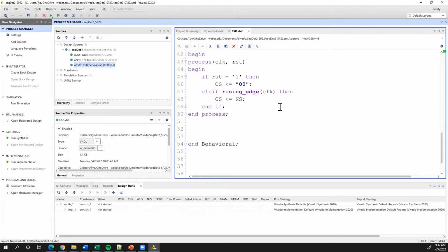One thing I want to say so I don't forget: if you ever run your simulation and it gets stuck at saying 0 fs, 0 femtoseconds, 90% of the time for you guys, the reason is because you forgot items in the sensitivity list. You've left a blank sensitivity list. This is allowed in the test bench and only the test bench. However, in hardware, it needs to know what's getting plugged into my clock port, basically. What am I looking for as an enable signal to say, let's run? Because that's what VHDL is doing: if anything in the sensitivity list changes, it runs through the process. In this case, it asks the question, is reset true? If it is true, it executes this if and ignores the else if. It's done.